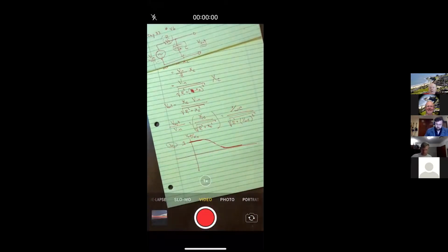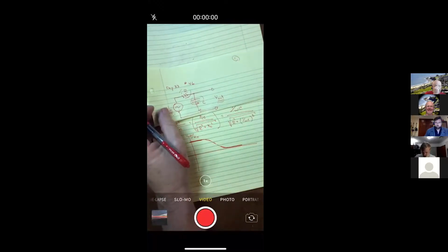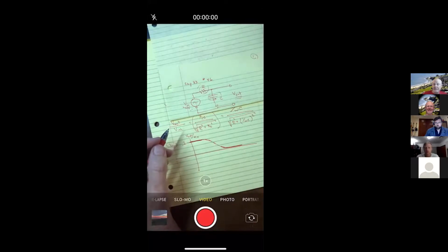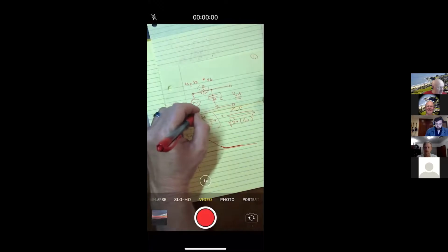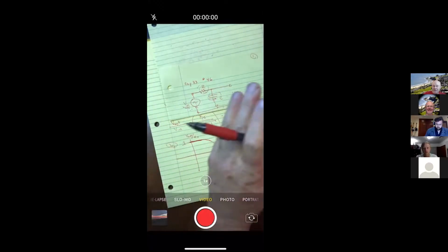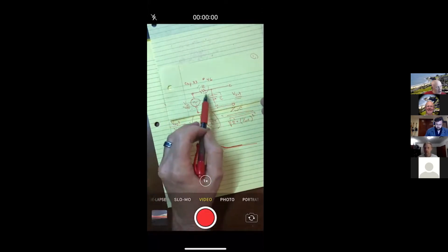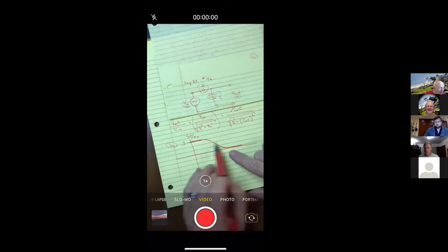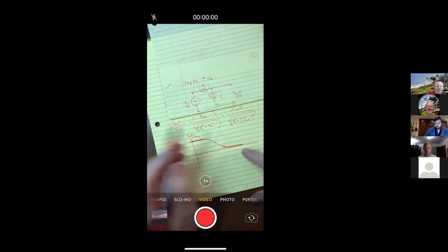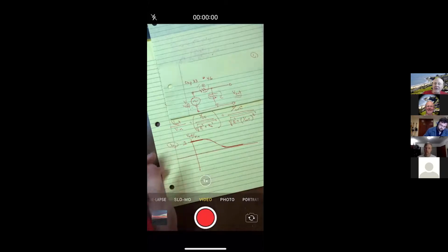And now you're maybe beginning to see why we call these things filters. They're filters because if you were designing an audio system, and your input has many, many different frequencies. Let's say you are an audio technician, and this is a band, and the band is playing all these different notes. Some of them are at a high frequency, some of them are at a low frequency. If you pass them through an RC filter, what comes out the other side is the low frequencies are just as strong, but the high frequencies have dropped away. So if you wanted to change the output sound and reduce the treble, but increase the bass, this is how you do it. This is your equalizer.